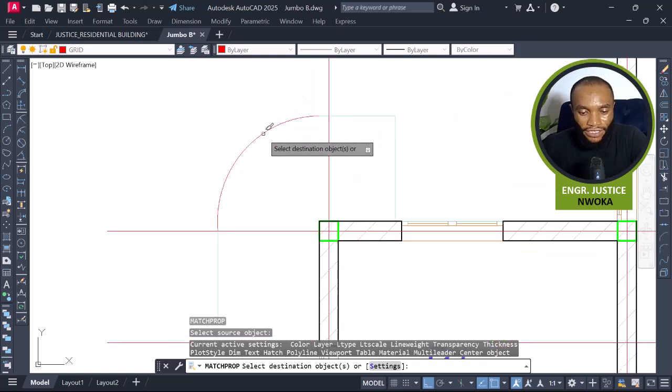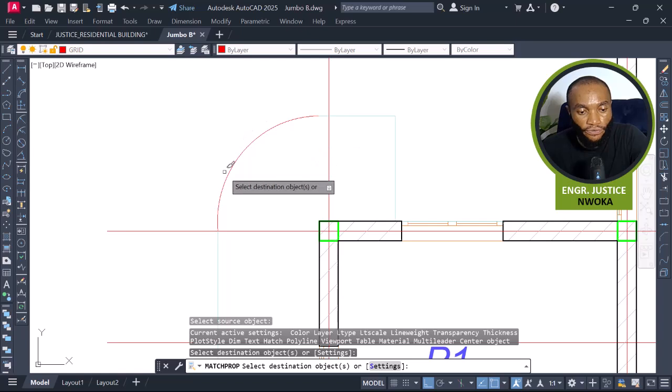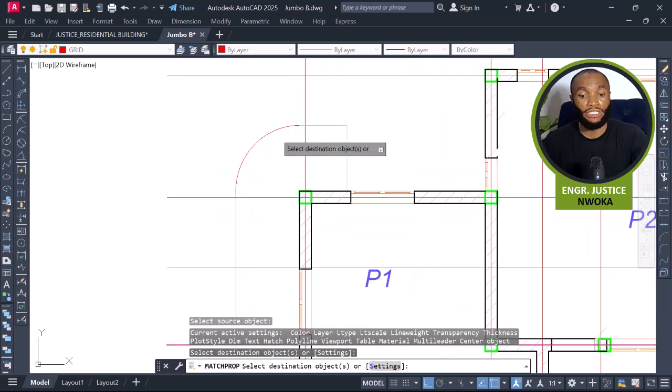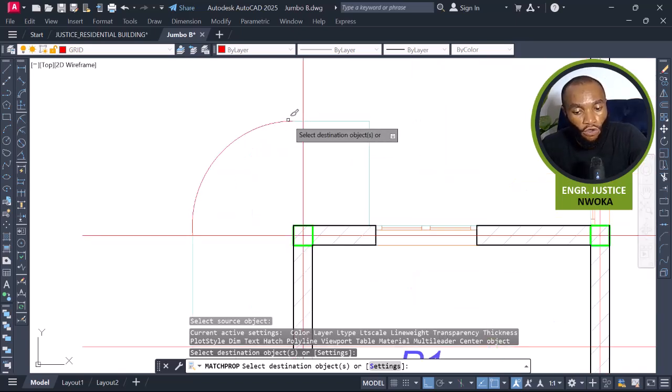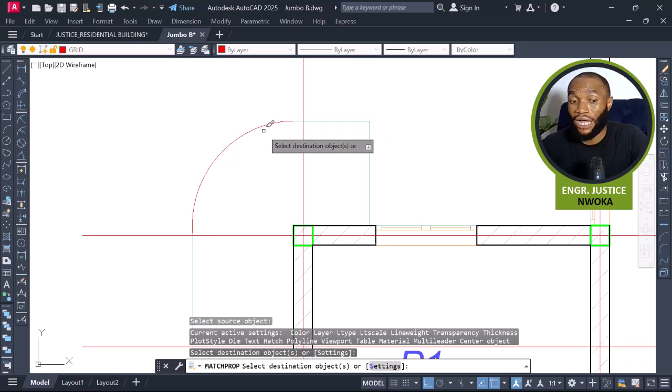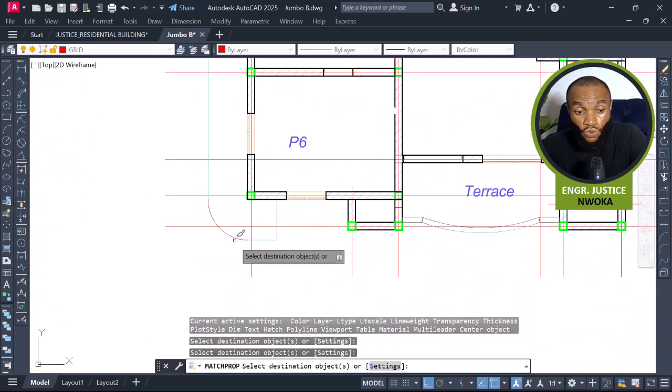But whenever you have a curve here, always convert this curve to being what? A grid line. Else you will have issues trying to get this perfect curve on the software when you're doing your modeling, because there is no perfect tool to get this curve. So always convert your curves to grid lines for it to appear on the software as axis. Okay, that's fine. So with this now, I'll convert all my curves to what? Grid lines. Okay, that's fine.